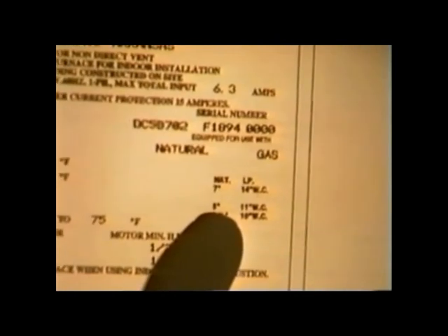A lot of these things we don't have to go through, but it does tell you here that we want a gas supply for natural. We're going to talk about natural gas. You can't hardly see this. You almost need a magnifying glass, but I'm going to review this with you in the job site form. But it says we want 5 inches supply gas pressure, 3.5 inches regulated.